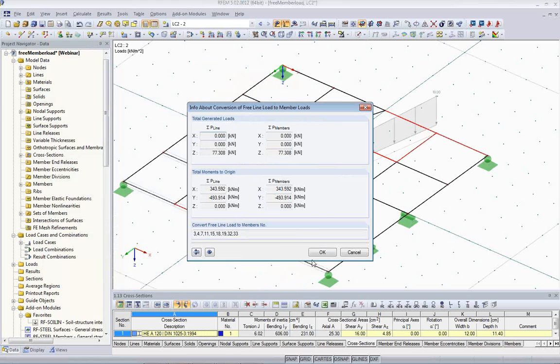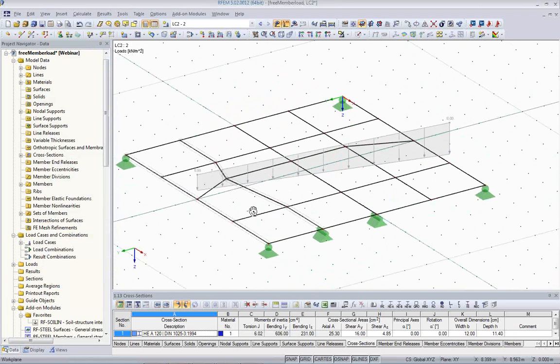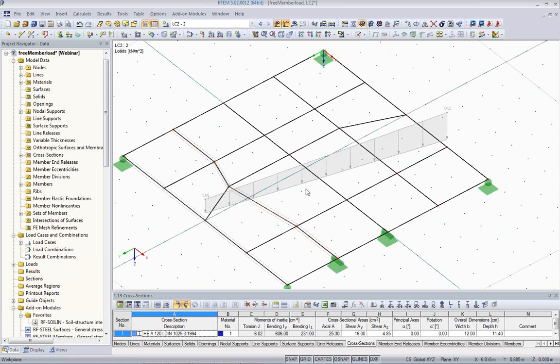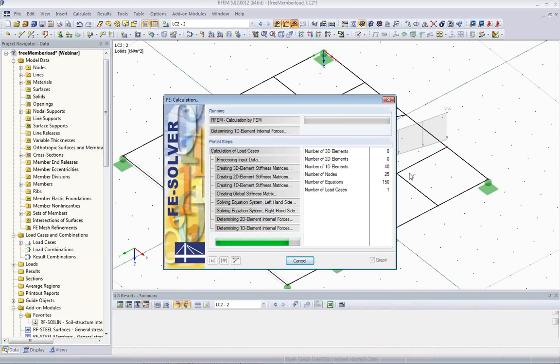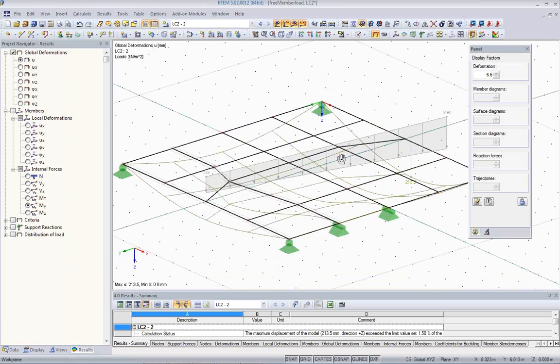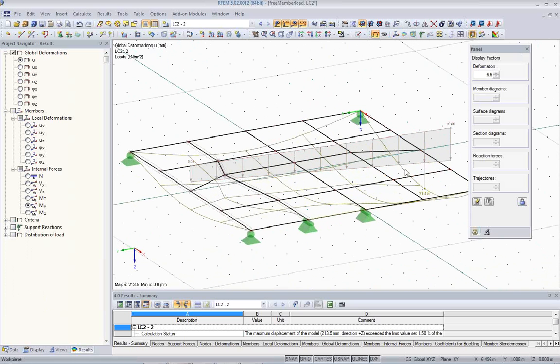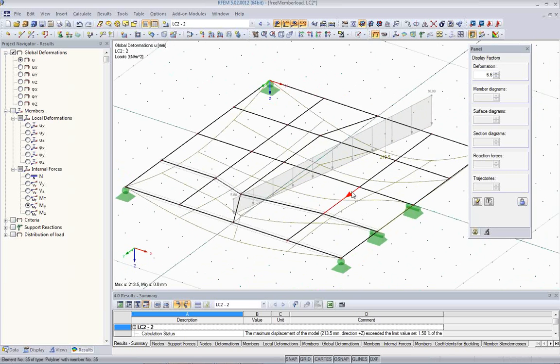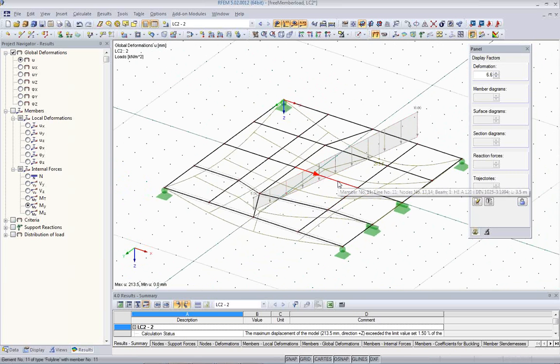Okay, and okay again. So this load is a virtual load which is on that grid, but it's not fixed to any member. So when I run the analysis, it calculates internally automatically the forces on this structure, and you get automatically redistributed force where the line load crosses a member. So it's also one tool that gives you more freedom.